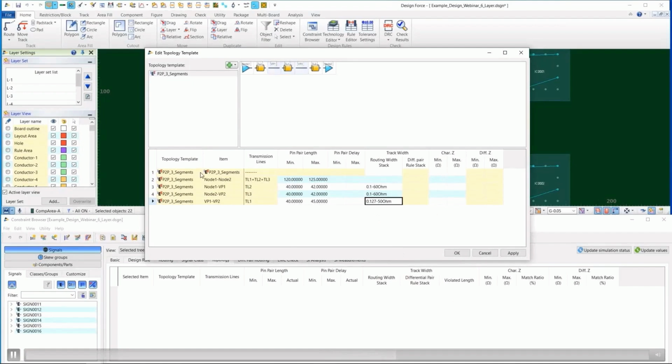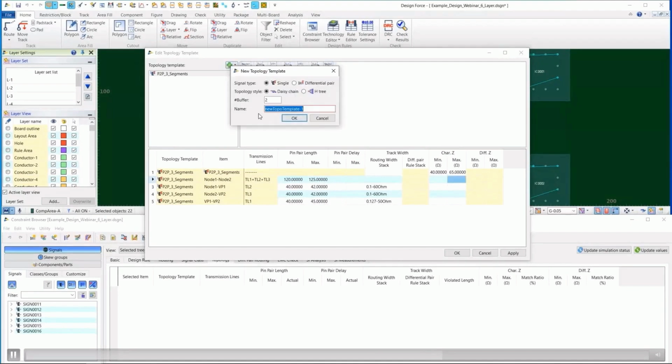This depends on the data sheets and topologies you get from the manufacturer. Also you can define the minimum or maximum impedances for your topology. That means later, if you have a line which is routed over a gap, you will get a higher impedance, so you can check your design against such constraints.